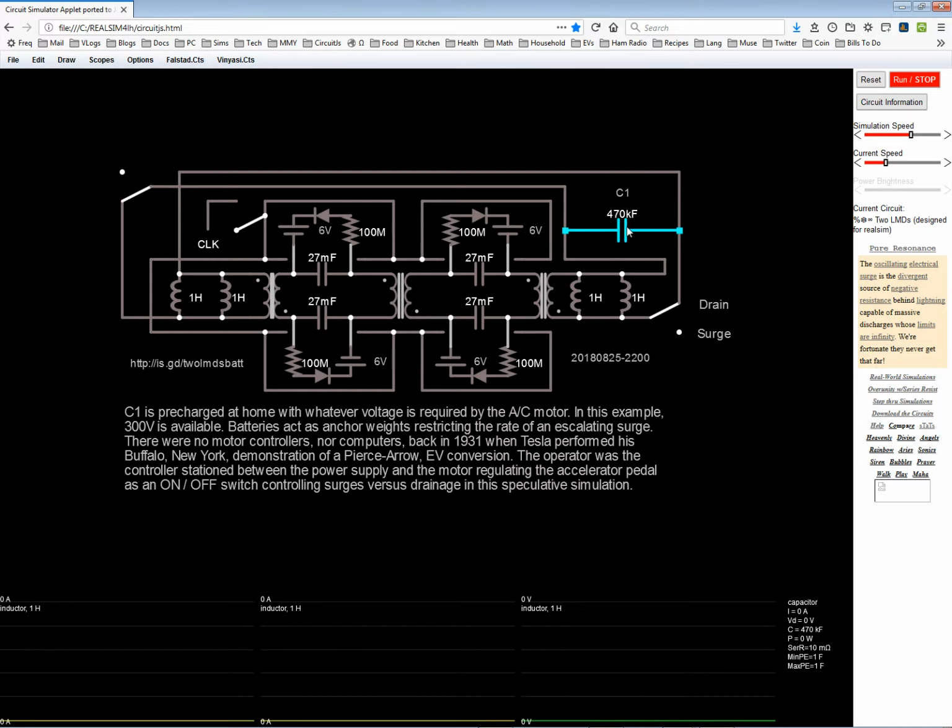Now, if this were to be started up from a cold start with absolutely no charge, no pre-charge to any of the components, in this configuration it takes approximately 2/3 of a second in real time to raise the current up to a level in which, when I disengage the surge and engage the drain, the current on the motor coils is what I want, the target of 50 amps for cruising speed, assuming I've already got up to cruising speed.